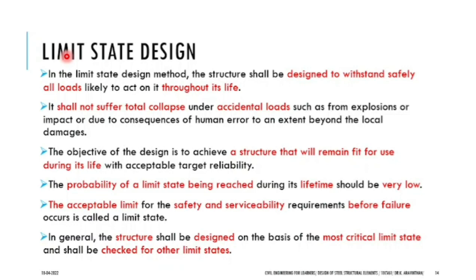Then do you expect your house to face a severe wind blow? So you should look into your code books, and the code books suggest that up to 40 meter per second, you can assume that as the wind force. And do you have a seismic zone? Yes or no? India has been classified into different seismic zones. What is the seismic zone of Bangalore? Zone 2.